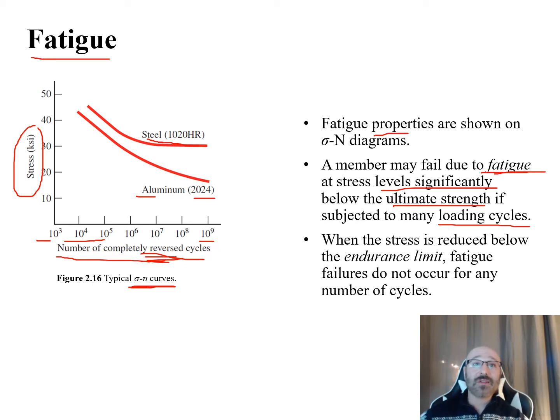This is important in the testing that you want to do. You want to understand not just, okay, if I use it once, it's great up to 1,000 pounds plus, no problem, call it a day. Well, no. You've got to do this life cycle testing. You've got to test for fatigue and see if this is going to affect anything.